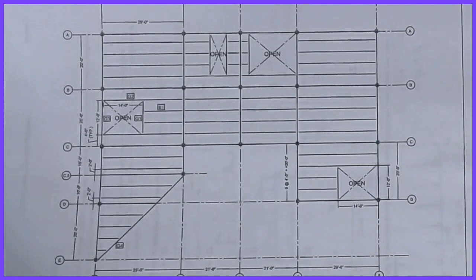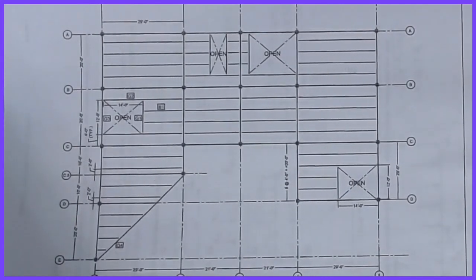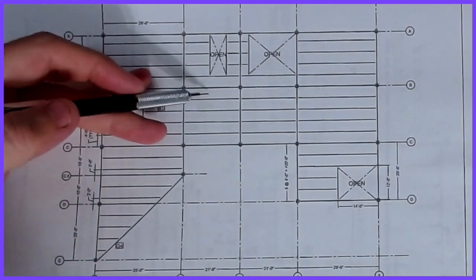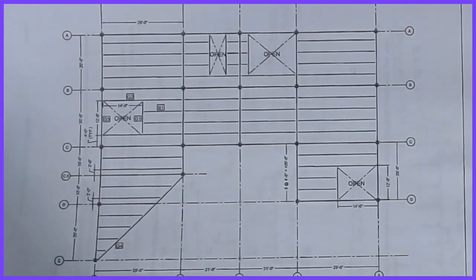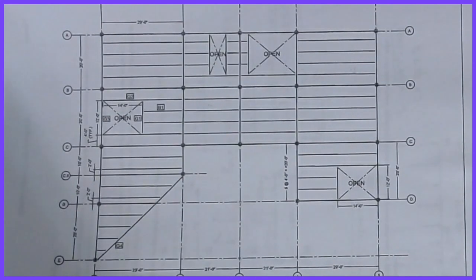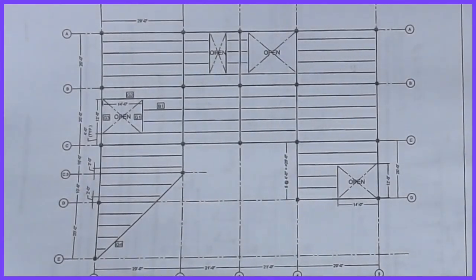Now, normally for plan views, we assume that since most buildings have some sort of concrete slab applied to them, the loads are acting on top of that slab, and the slab is being carried by the framing. What we're after in this case is figuring out what loads would show up on the framing itself. When you get to slab design in your concrete class, you'll handle the slab itself a little bit differently. But for us, we're thinking more of the structural steel or even the concrete members below that are holding it, part of that main structural system, if you will.